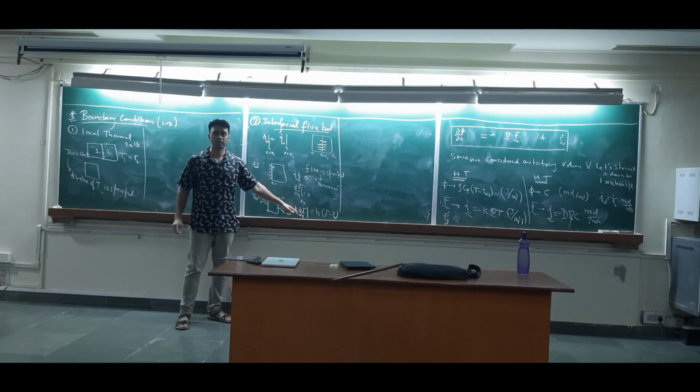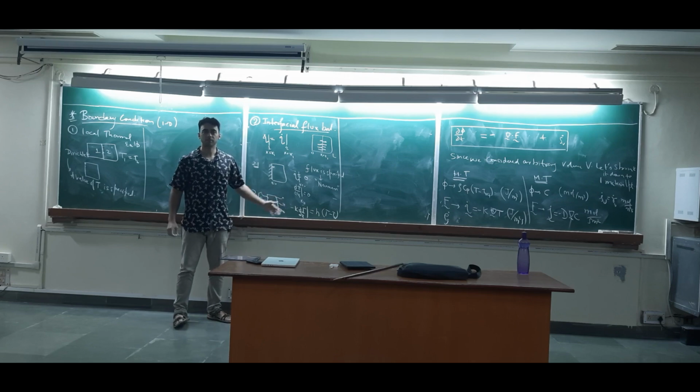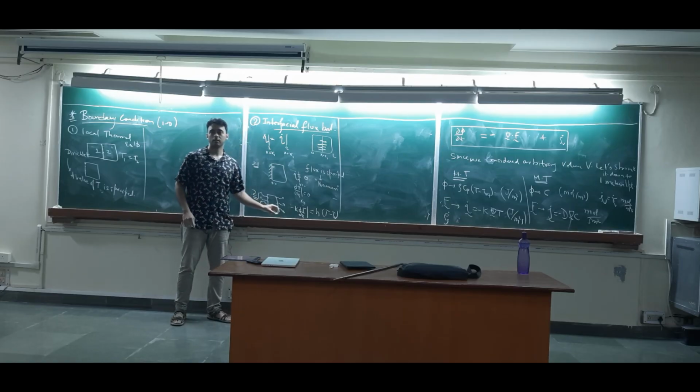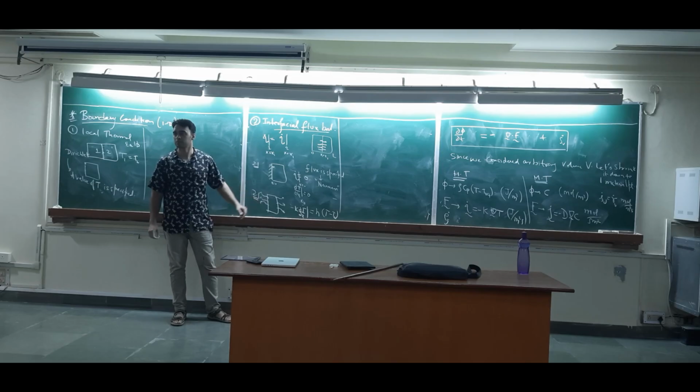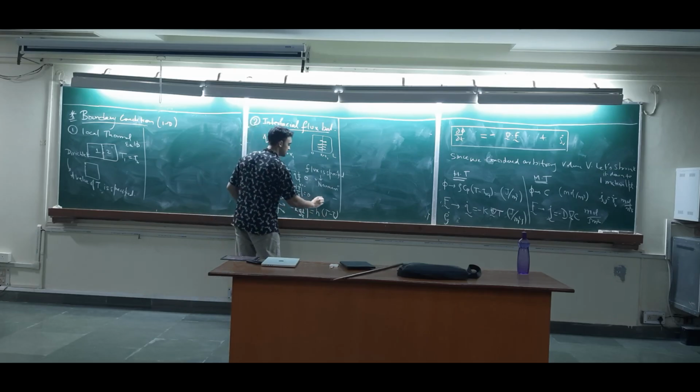Also the flux is specified, right? We are saying the conductive flux is equal to convective flux. Specified. So is it Neumann? Think about it. It's not really true. Flux is not specified. Flux is given as some function of temperature, right? So this is known as mixed.